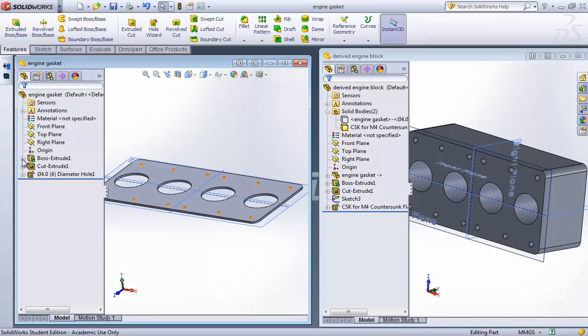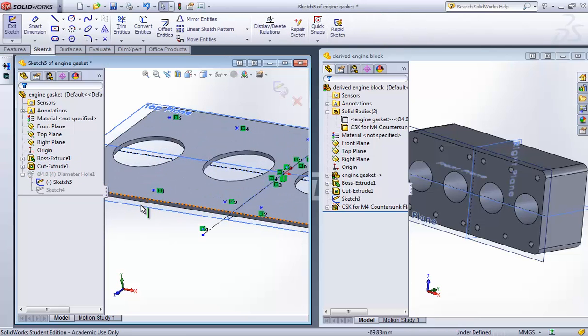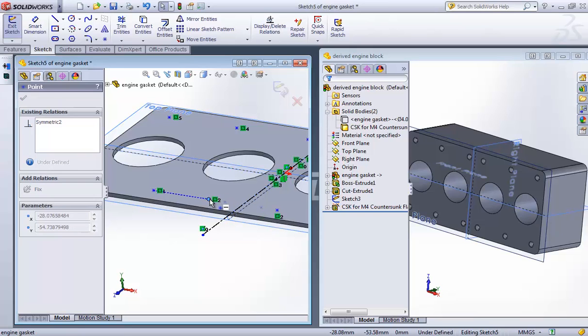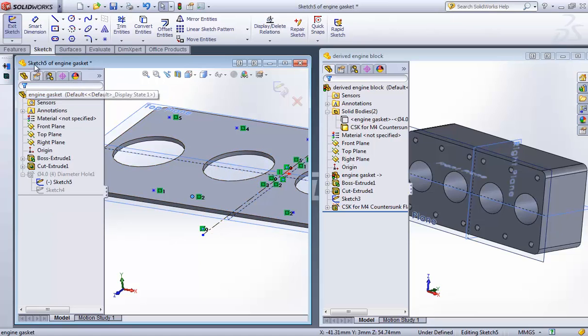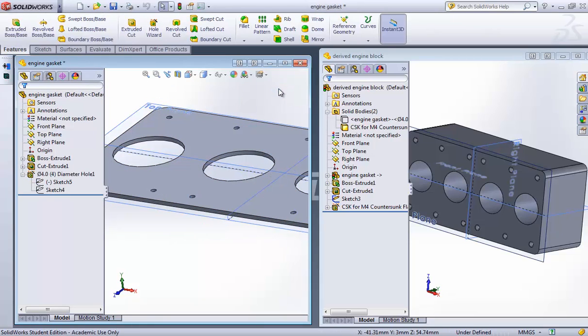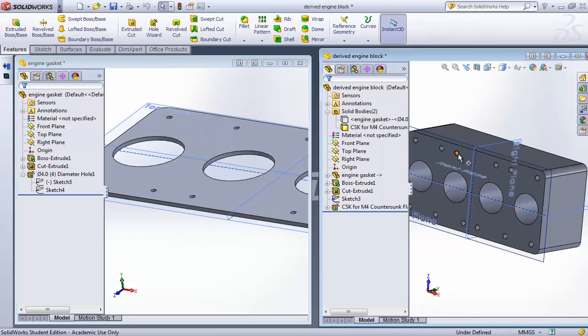a linear effect. So I'm gonna go, I could have chosen something else, something easier to tweak. So I think it's this particular sketch here, which contains the position data of the holes. And if I were to tweak that out, so I'm gonna leave it here. Right, confirm that, commit to that, and the holes have moved, as you can see. Well, this one's moved. If I click on this file here, I'm sure you can see the difference there.